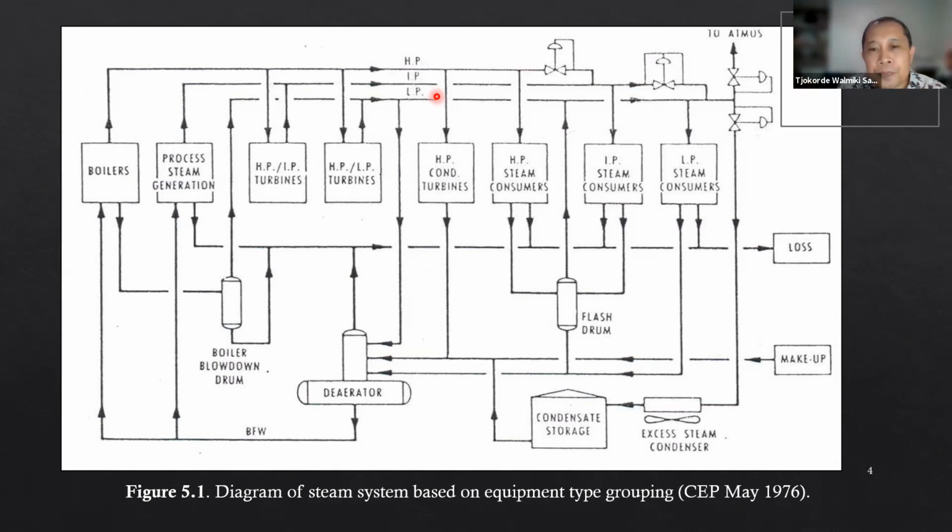Okay. Right. So that's the reason why if your high pressure steam requirement is significantly lower than the intermediate steam or lower pressure steam, we do not produce steam at lower pressure and then compress it. Okay. But we use two separate boilers typically. Okay.